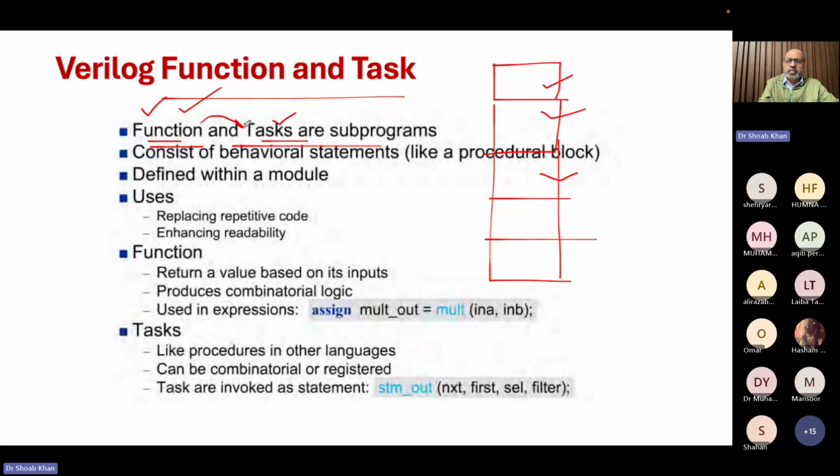So some of the divide and conquer things will be ported as a function or a task, and this takes me right to the architecture that we discussed, where we have those blocks: majority, choice, sigma 0, sigma 1 in the hash function. So we would rather prefer to define all these four as functions. Function, function, function, function, or even a task. I don't mind if you do this.